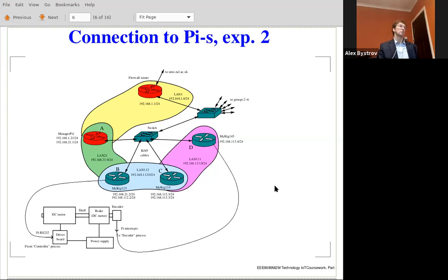So you will draw a conclusion, which will be that networks do not help construct control systems, and that the problem can be alleviated perhaps by changing the parameters of the control system, reducing their values. Typically, when you reduce the values of the coefficients in the PID controller, the controller becomes more stable but more sluggish. So that will be the second phase of the experiment.